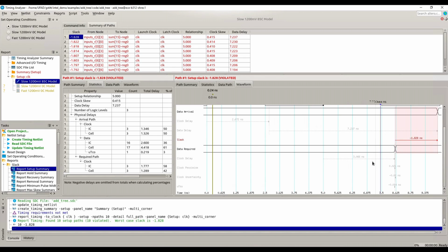And then on top of that, there's this setup time down here. Intel calls it the micro setup time, but it's not micro, it's negative 0.014 nanoseconds. So basically, we subtract a little bit of time from this clock delay, and that gives us this data required time.